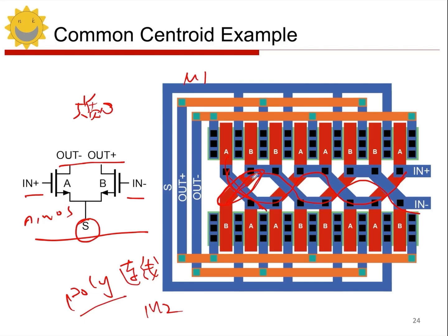so I have to use M1 when crossing it. So if I connect B and try to cross it over, I can't use M1 anymore, right? Because that would short circuit M1. There definitely has to be another layer. If I still use metal, then I would have to use M2, right? In that case, I would be wasting a layer of metal here, actually. So, what can I do? I can skip using M1 and directly use what? I can directly use poly for the connection of B, and that would solve the problem, right? Using poly takes care of it.